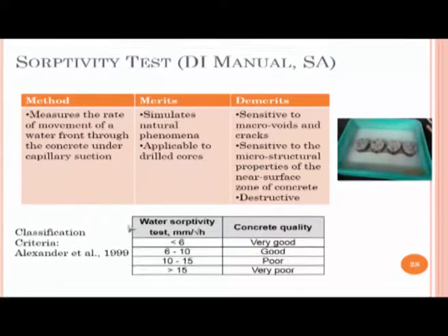The sorptivity test is very simple. Again, you use the same specimens that were earlier used for oxygen permeability. Please remember, sorptivity is done on specimens that are similar to those for oxygen permeability. I will show you the method of specimen preparation on the board.